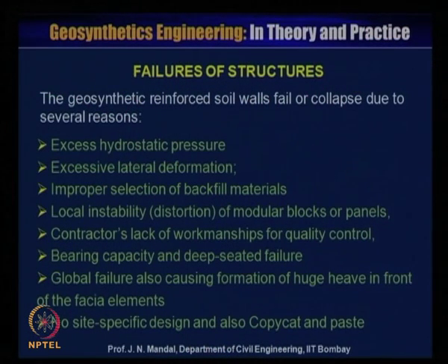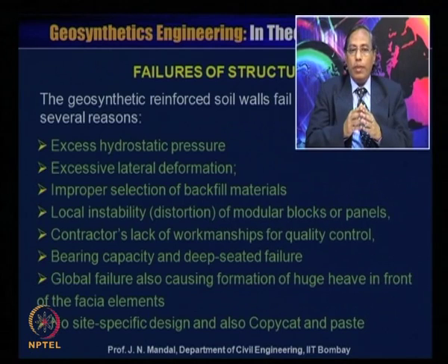It is also very important to check whether the modular block or the panel satisfies the local stability or not, because every block or panel has its own weight, and you have to check for the shear and moment and check whether this modular block or the panel is satisfying the local stability criteria or not. Then the contractor's lack of workmanship for quality control.